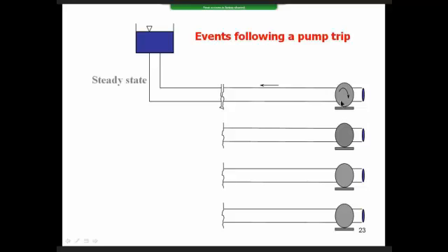The next slide I want to give you an idea why this can be a pretty serious problem. Now, this is sort of the classic problem that you want to avoid, if you're looking at piping and you have a situation where you're pumping into a pipeline where there's a reservoir or a tank that's elevated. This is always a situation of concern, because if you trip your pump and your water does cavitate, you've got a substantial head to collapse the cavity.